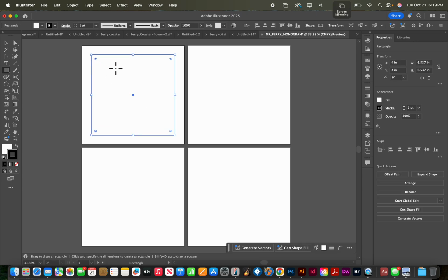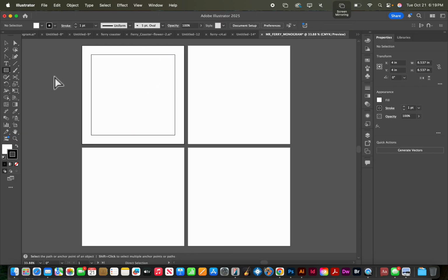And let's say I'm not in the middle. I can just look up to the alignment tool, right? If I'm in the square, if you go up to your options bar at the top, we'll see these alignment tools, right? So we want a horizontal align and a vertical line. But I was perfect, so you don't notice it. But watch, if I move this and I'm still selected, I can click vertical and click horizontal, and now we have it perfectly in the center, okay?